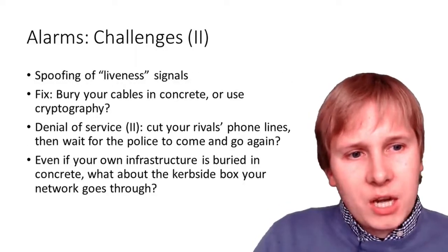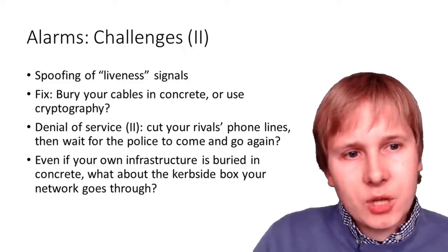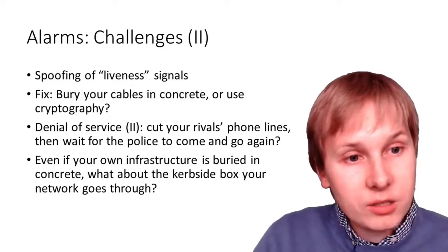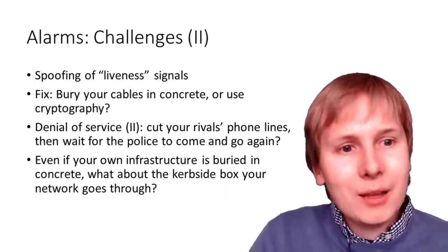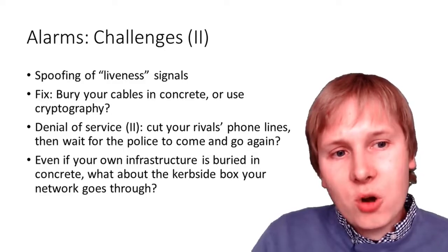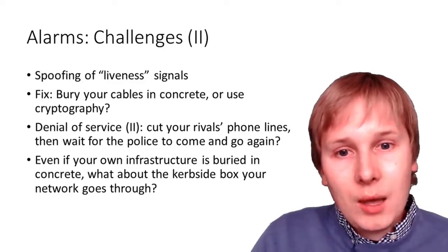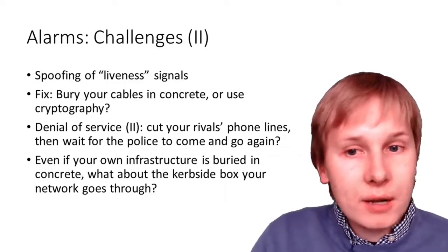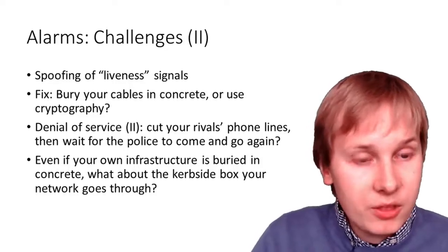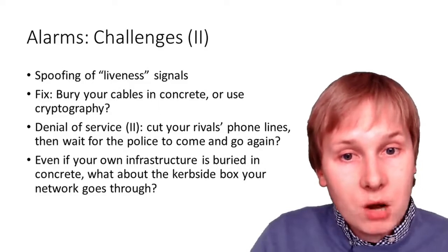And then there are other challenges around actually trusting what your alarms are telling you. So alarms are often designed so that they've got liveness signals, so that if someone just cuts the power to them, that will sound the alarm. But if someone can get control of that and spoof the signal, then you can't rely on it anymore. And there are usually two ways of trying to solve that. Either you bury your cables in concrete and have multiple of them so that it's very difficult to get to at least all of them, or you use cryptography.